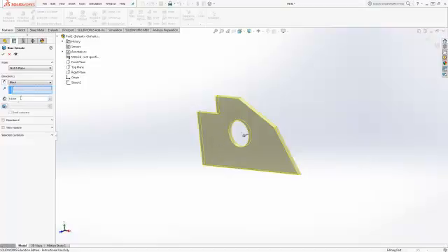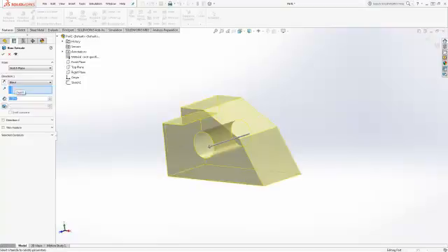All right, notice it gives me a distance. So blind is a distance that I want to use. So blind, how deep is the whole thing? It's 1.5. Now, I guarantee I'd have somebody want to try to make this 0.25 thick and then try to build that bottom off of it and then try to build the other one. Well, that is one way of doing it, but it's not the most efficient way. So anyway, here we go. We've got this. It gives me an example of what it's going to look like, which is cool.